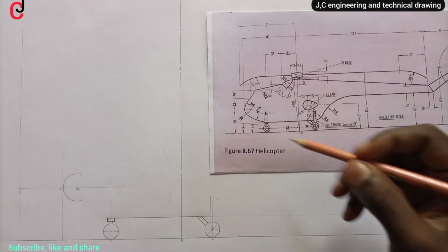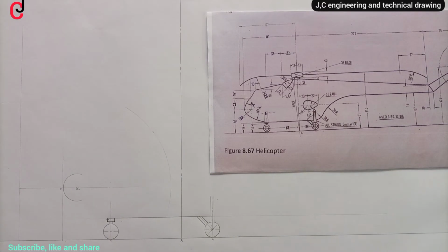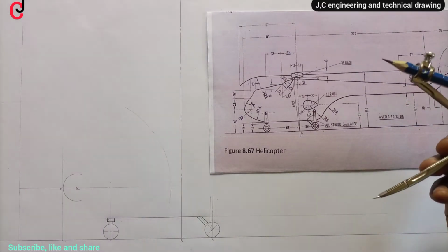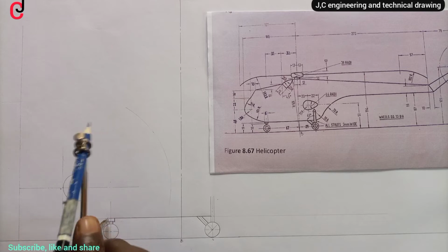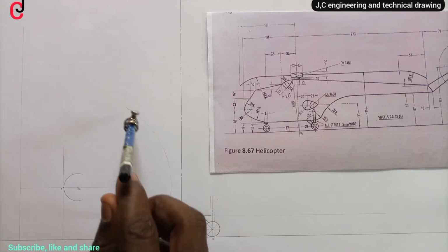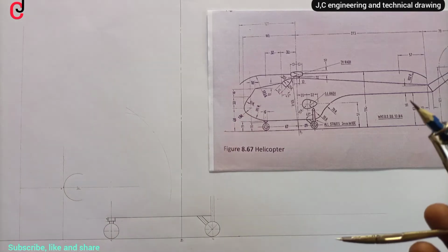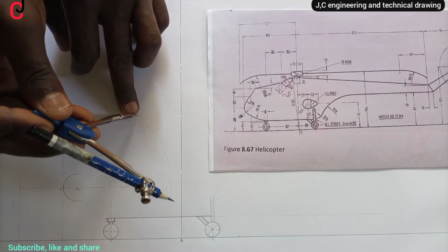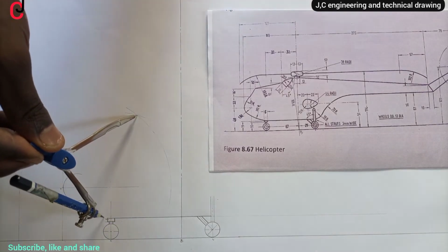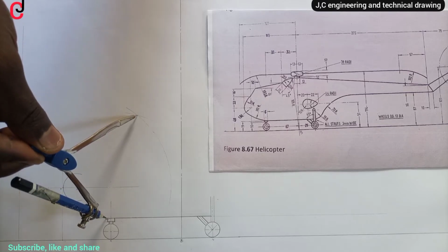and then we'll open our compass to 101 millimeter radius. So we succeeded in opening our compass to 101 millimeter radius. Place it at point O3. Then we'll bisect our arc. Now using the same radius of 101 millimeter, which we've measured, at the point of the intersection, we'll draw an arc touching point O3, and it's also touching the circumference of our circle.